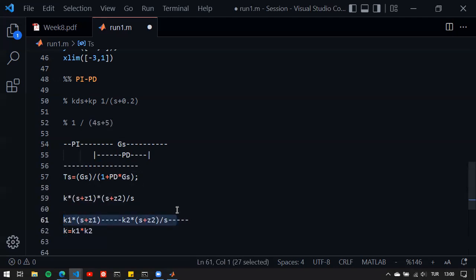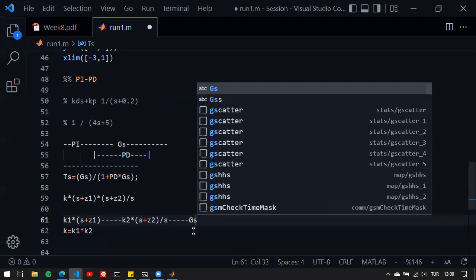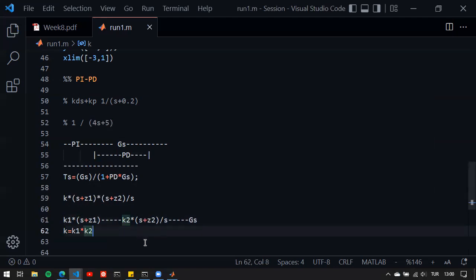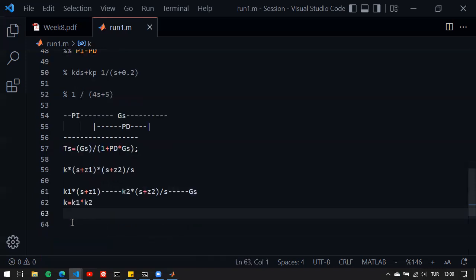It's basically the same. The only difference here is that we have used a PD controller and then a PI controller, but it's again the same controller. And if you have a system here, GS, the closed loop, the numerator and the denominator will be the same. Nothing to change really. We've taken them apart, used the PD part and PI part. The only restriction here is that the gain distribution should correspond to the same gain. Since we have them in a series, we should multiply the gains here. So if this is okay, then understanding the PI-PD controller will be easy.